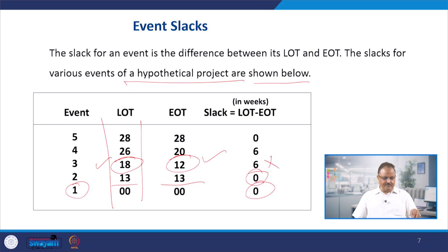No, we want the path which is a very critical path, with the minimum possible time, the earliest occurrence time possible in that path. We are going to find out that path, and there may be some cost increase. When you reduce the time, cost has an inverse relationship here. So when you reduce the time, cost increases, especially the direct cost.